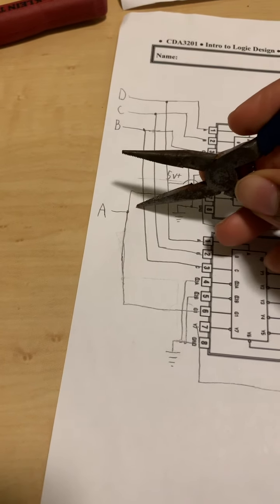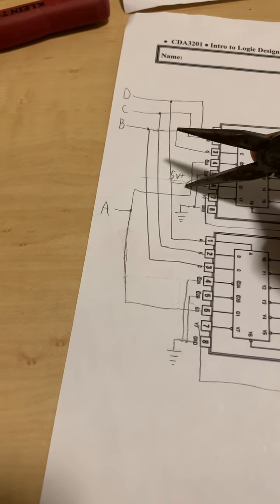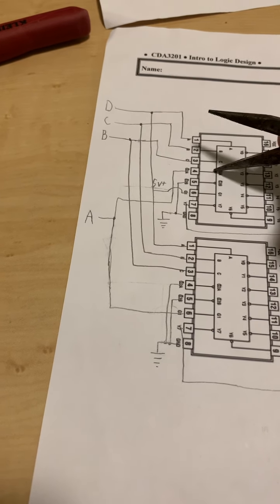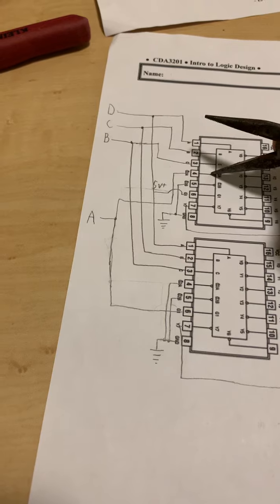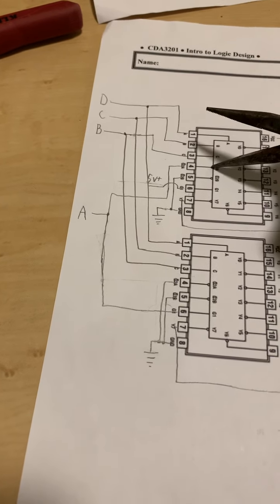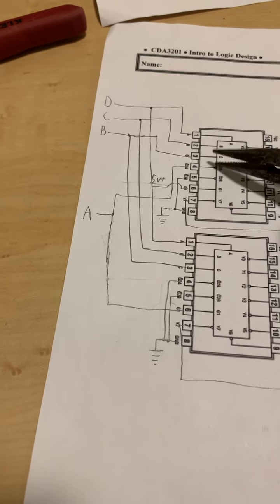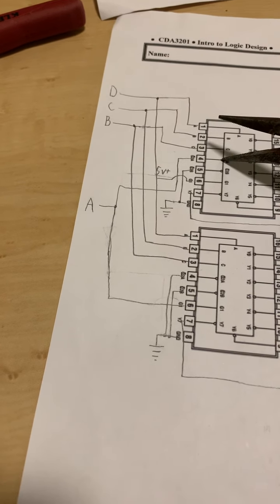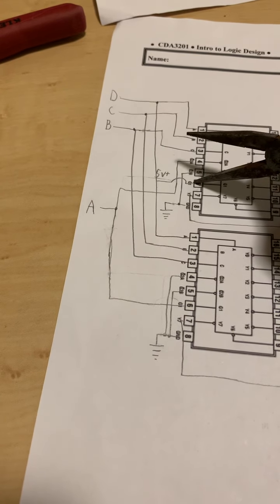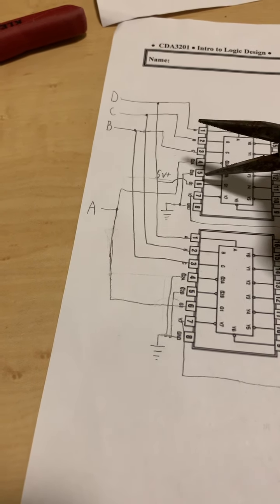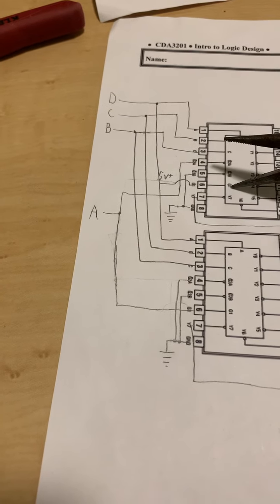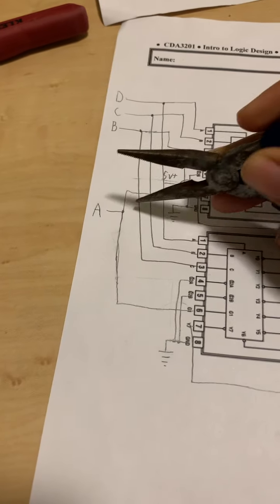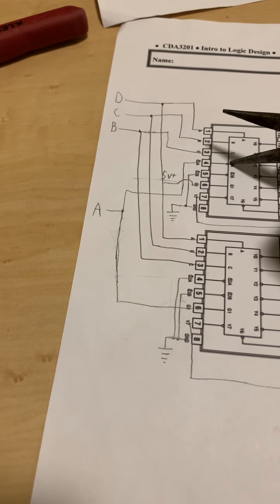So what I did is when A is 1, it would go to the ground, but this makes it low. This is low, so it reads low inputs. Because this is high, it would turn this off. However, this 5 volt would be on all the time, which would be going into the high input enabler. Because this would always be ground, this would always be high, and A would be determining if this would turn off or on.